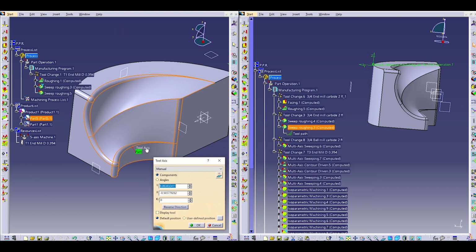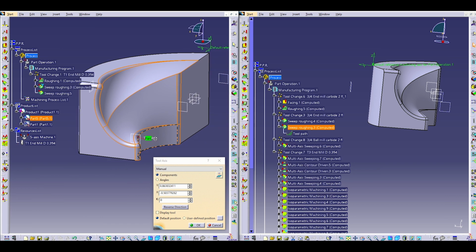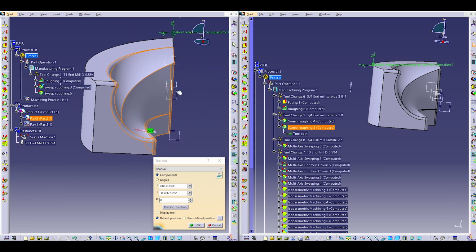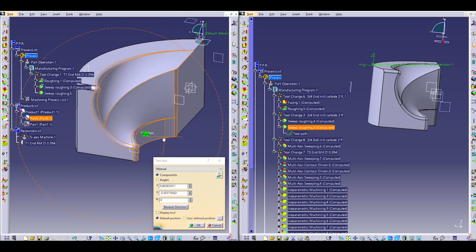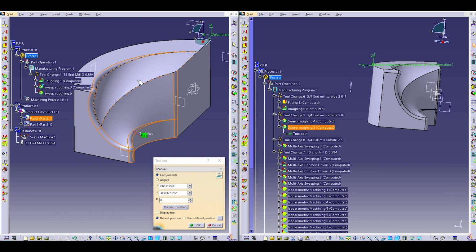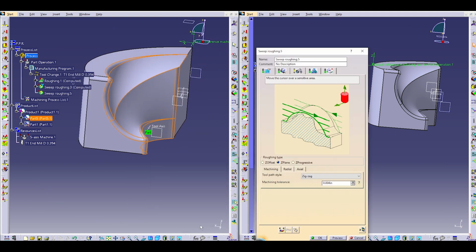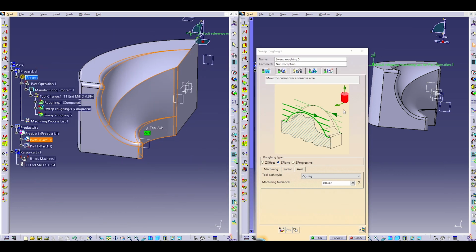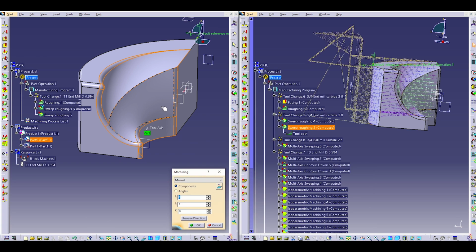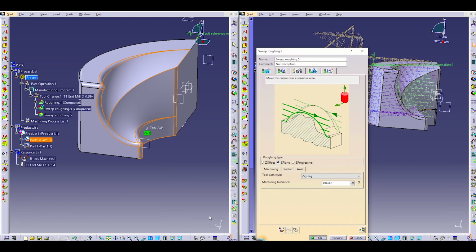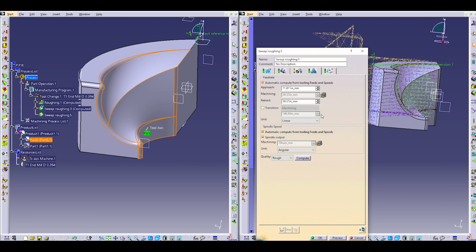Again, selecting that tool axis is kind of important, which way the tool is going to be coming from, which can be any direction you want it. I like to click the face, or a certain face that'll be the optimum angle to cut all the surfaces. And again, you want the arrow pointing out towards where the tool will be coming from to cut the part. So it'll be pointing away from the part.